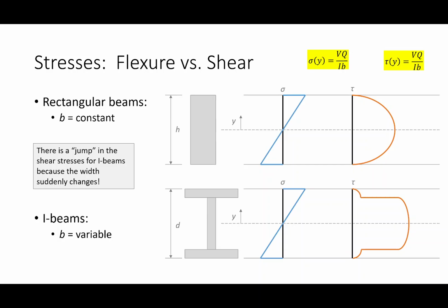Does that make sense? So if we were looking at a steel I shape and we were thinking about shear, where is the primary amount of shear carried in a steel I-beam? In the flanges or the web? In the web, right? The flanges, here and here, really aren't seeing hardly any shear stress. But the web, this part in the middle, is seeing a lot of the shear stress. A really simple way of thinking about it is that the flanges are responsible for carrying the moment capacity, and the web is responsible for carrying the shear capacity. So flanges dictate how your beam behaves under moment. The web dictates how your beam behaves under shear. So if we're going to start looking at shear capacity, we're going to focus on the web. Does that make sense?